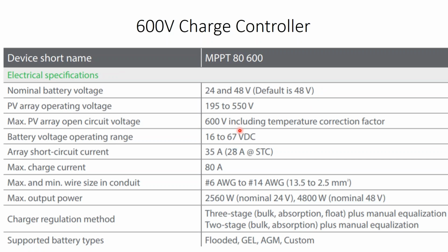Just remember that a 48 volt battery, that's the nominal voltage. Usually a 48 volt battery can go all the way up to 60 volts. It just takes too much energy to charge it up to 60 volts. You would only be charging it up to maybe 50 or 51 or 52 volts during a battery maintenance cycle.